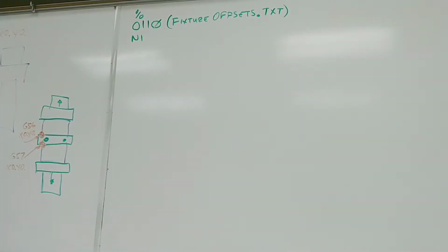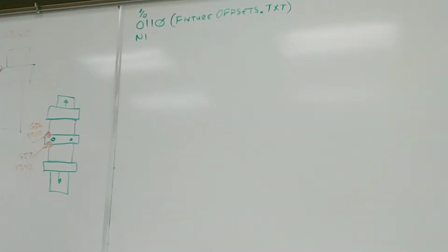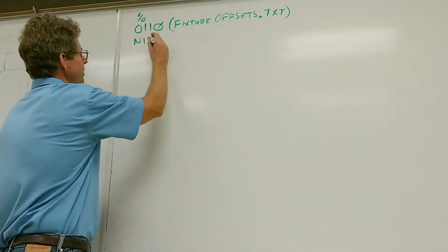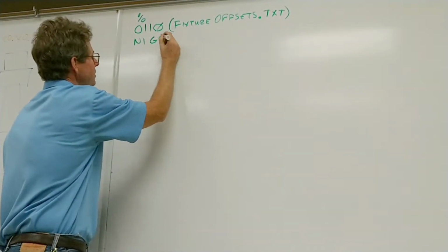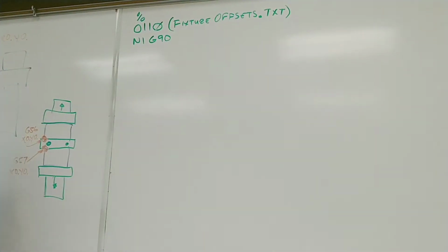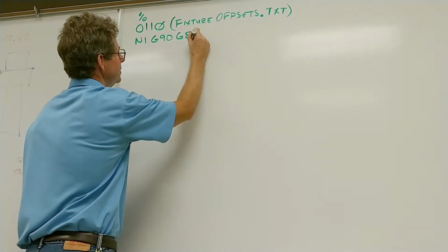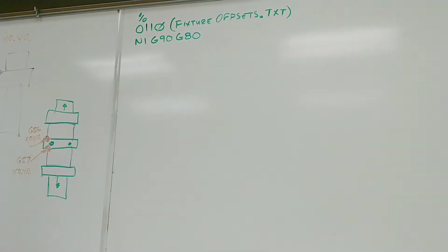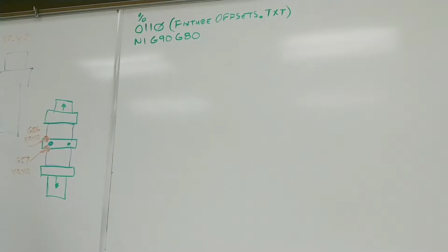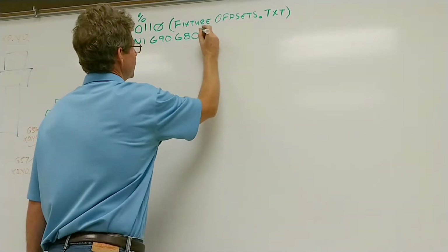Okay? The first thing we normally put in an NC program is what's known as a safety block. And it doesn't make anybody safe. But what it's really doing is it's setting the machine up into a known modal position. So G90, we're telling the machine that it's in the absolute mode. If we want it absolute, if we want it incremental, we put that right there. Okay? Here are some additional codes we haven't really talked about much yet. G80. G80 is a command that cancels canned cycles. Okay, I want to turn off canned cycles. Make sure nothing is active when I run my program.